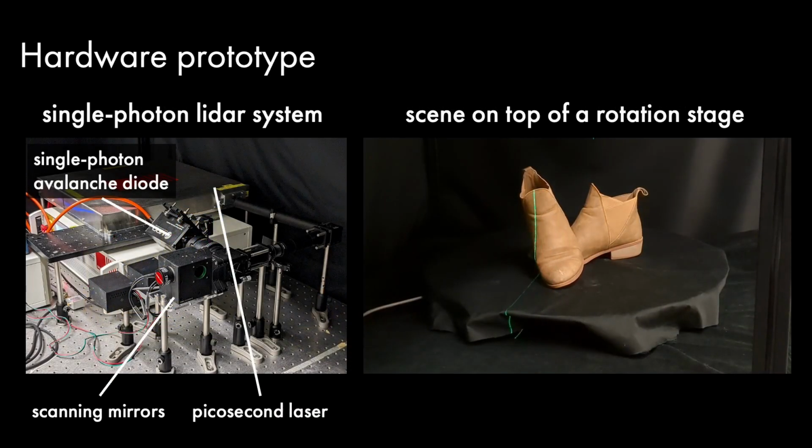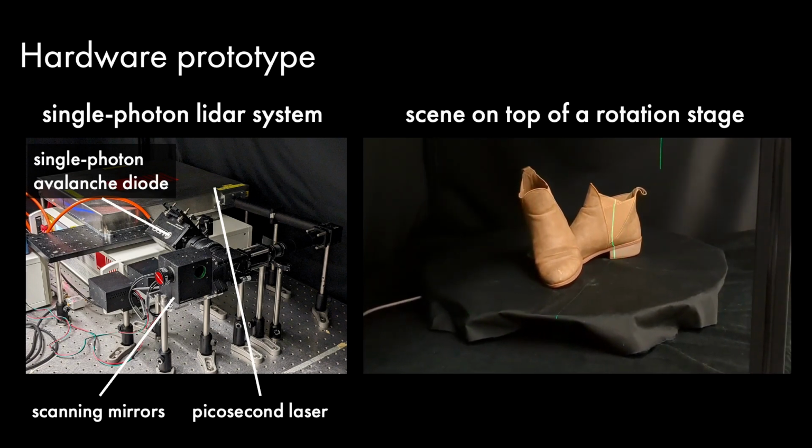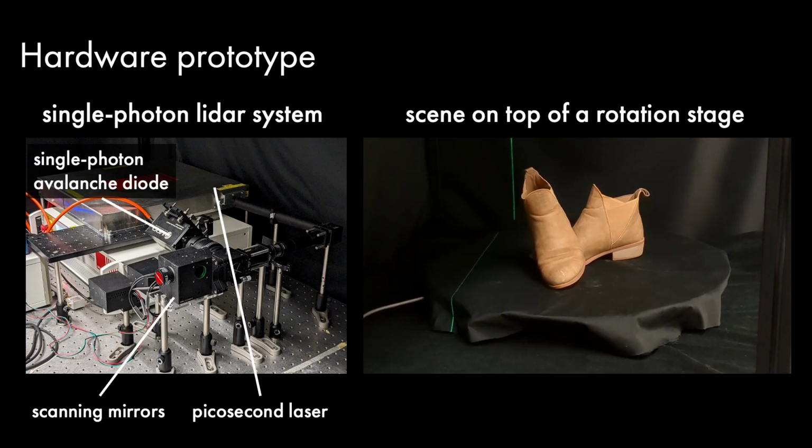We also test our method on a dataset we capture using our prototype single photon LiDAR system shown on the left. The hardware system contains a picosecond laser that shares an optical path with a single photon avalanche diode. We scan the scene using a 2-axis scanning galvanometer. The scenes are mounted on a rotation stage to facilitate multi-view scanning.